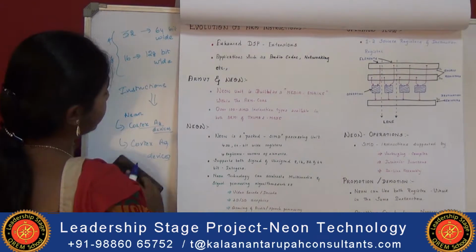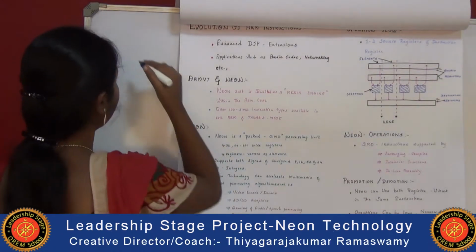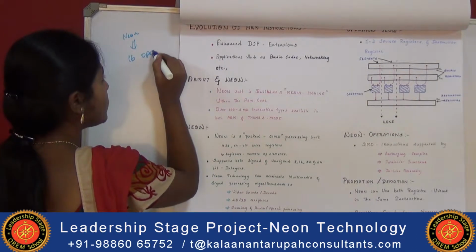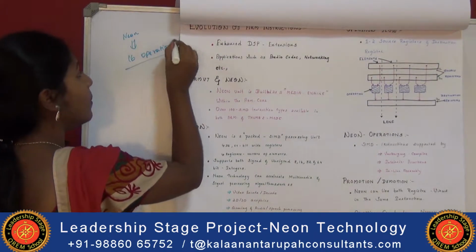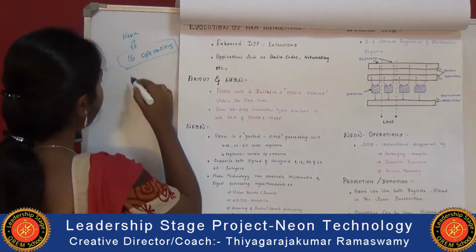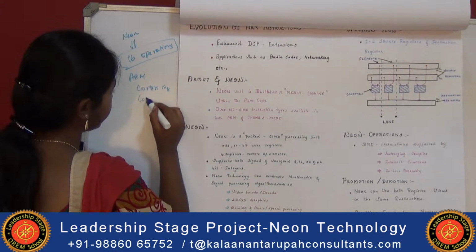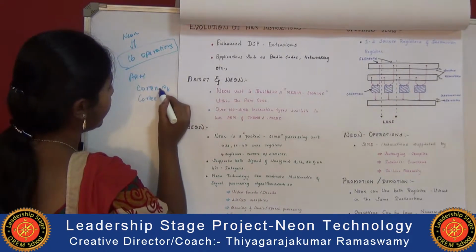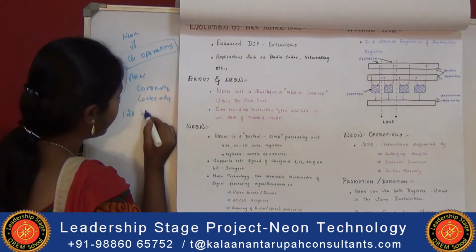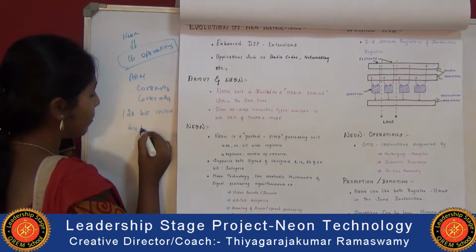This is about Neon. Particularly, Neon has 16 operations. That is, Neon supports 16 operations at the same time using SIMD. 16 operations can be performed at the same time using Neon based on that SIMD, and all Cortex A8 and A9 devices both have the capability to store 128-bit vectors, but they can execute only 64 bits at once.